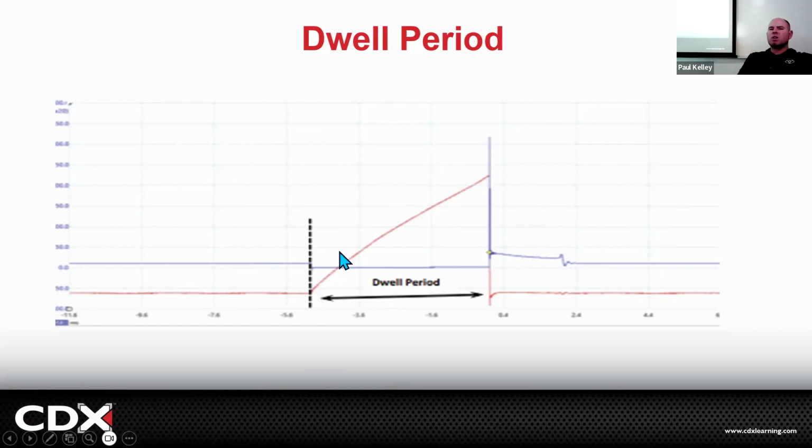If I had a mouse chewed primary wire, do you think it would ramp up like this? No, because it's open. It's like if you have a chewed wire to the light bulb, is the light bulb going to light? No. That means if this coil is not getting the 12 volts and ground from the primary, it's not going to ramp this way. If it doesn't ramp this way, you know that the problem's in the primary side of the circuit. You set a primary circuit code. You send that in a picture along with a chewed wire to some guy, and he says it's not the spark plug. How dare he? The spark plug would have no effect on this, right?